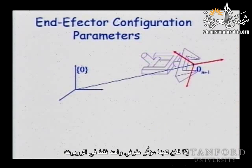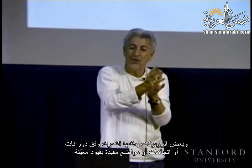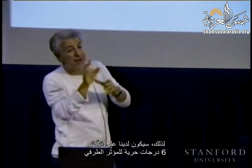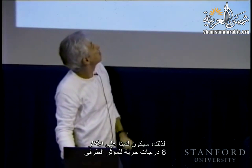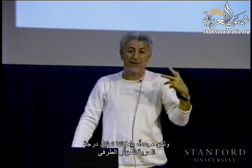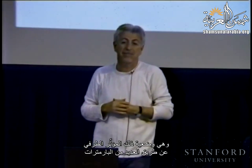So if we have just one end effector in the robot, essentially we have just one rigid body. At most we need, depending on the freedom, because some robots can only move in the plane. Some robots can move with restricted rotations or orientations or positions. So at most we are going to have 6 degrees of freedom for the end effector. But again, we can represent that freedom of the end effector, that is the configuration of the end effector, with many different parameters.